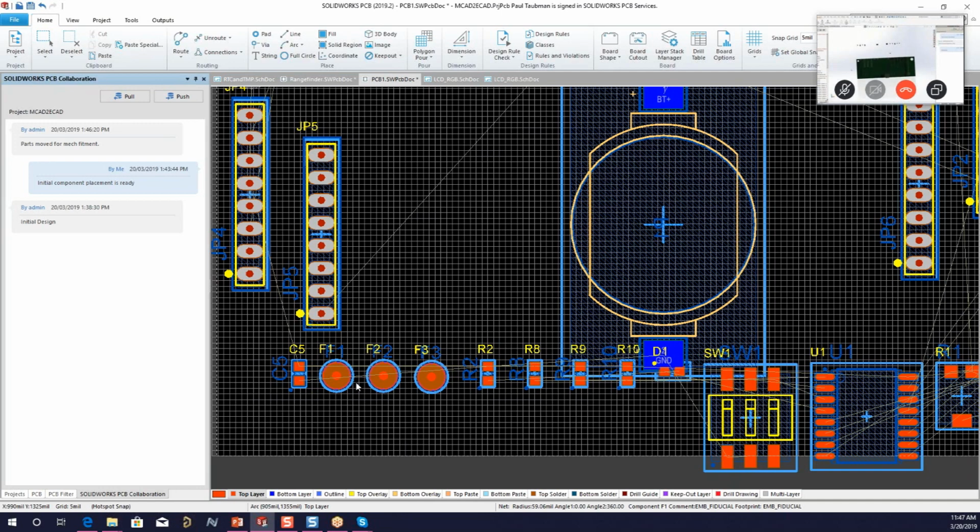Yep, very true. And not to get too deep into the tool over here, but there's what's called the design rules, and those get set up to make sure that we keep certain clearances, primarily to make sure we don't short anything, but also just for mechanical, actually manufacturing purposes as well. We can't make things down to the micron level just yet. So we have to be very realistic about what we do to ensure that it can be manufactured.